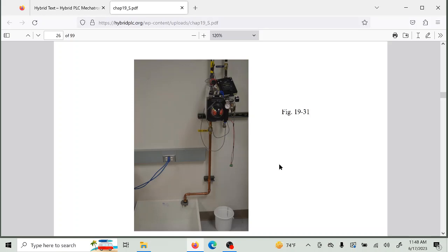Now, this required instrument air, and one of the problems that we had was that the instrument air had water in it. And again, if you have bad instrument air, you will mess these valves up royally, and water is a killer to these guys. So water in this line right here, which is supposed to be dry air, will mess these guys up royally, and it did.